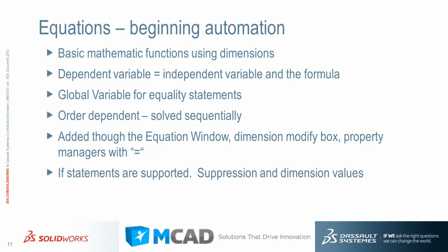So now we can start looking at equations, and I think of SolidWorks equations as beginning automation. They are basic math functions using dimensions. They're always in the form of the dependent variable, an equal symbol, the independent variable, and the formula, the expression, any constants you want to use, any other functions, sine, cosine, trigonometric functions of the like.